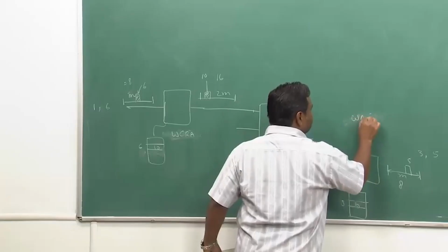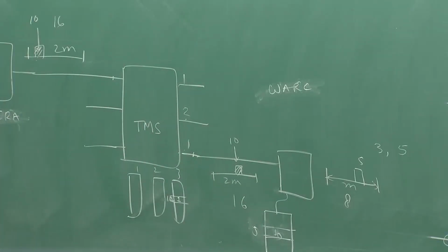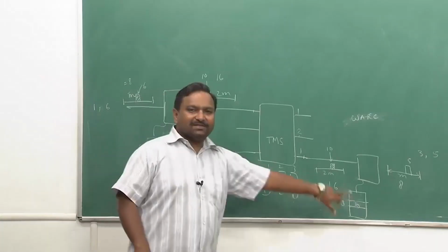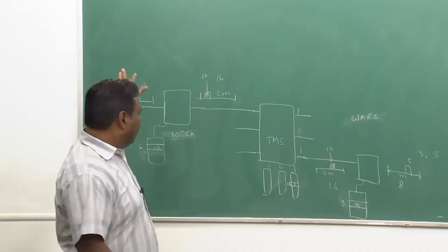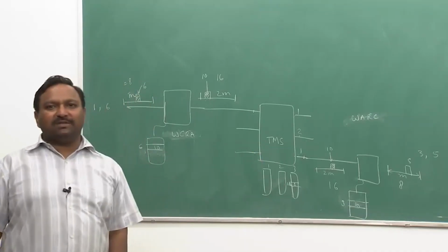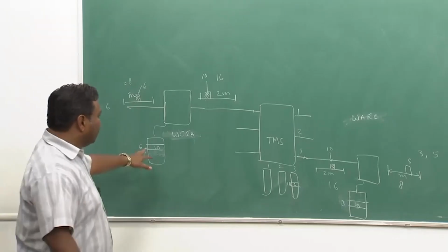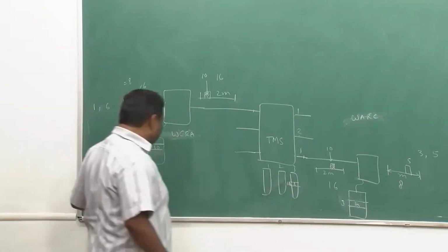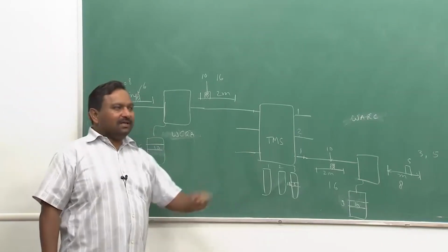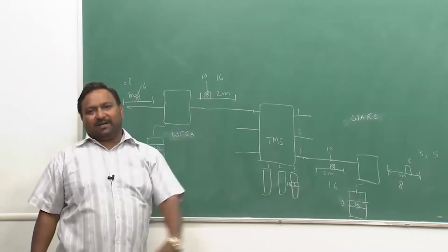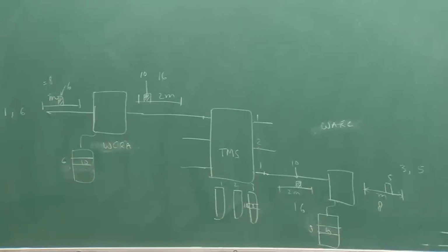If I use this, life is cool. For one particular connection all memory locations are the same. So, I can use one single address bus for addressing all the control memories simultaneously while writing into them. Because all these control memories have to be communicated from the central controller, which will write words into this, which will cause a connection to be set up through this digital switch.